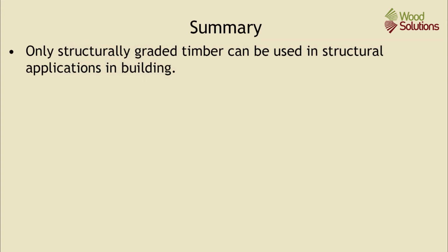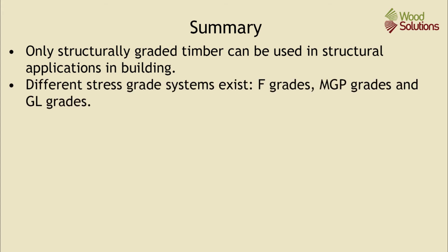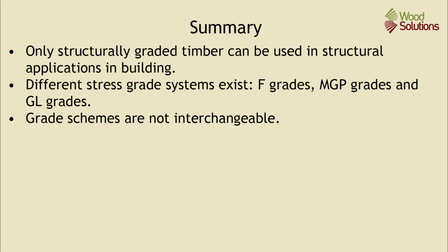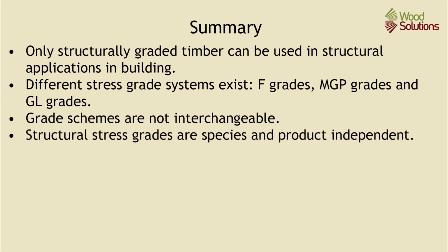In summary, only structurally graded timber can be used in structural applications in a building. Different stress grade systems exist: F grades, MGP grades and GL grades. Grade schemes are not interchangeable, and structural stress grades are species and product independent.